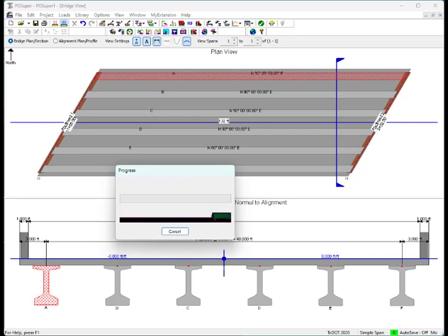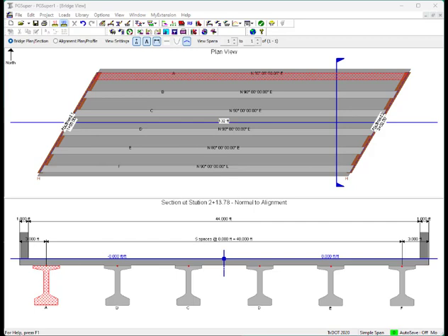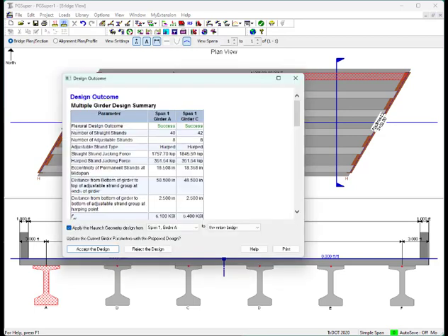The structural design algorithm makes a highly educated guess at an optimal design. I say guess because it may not always converge on what you consider to be optimal. Finding a design is a nonlinear process. At the highest level, the design algorithm uses multi-level Newton's method iterations to attempt to converge on an optimal strand layout for the lowest possible concrete strength. The process is simplified for TxDOT design since they do not consider girder lifting and hauling.